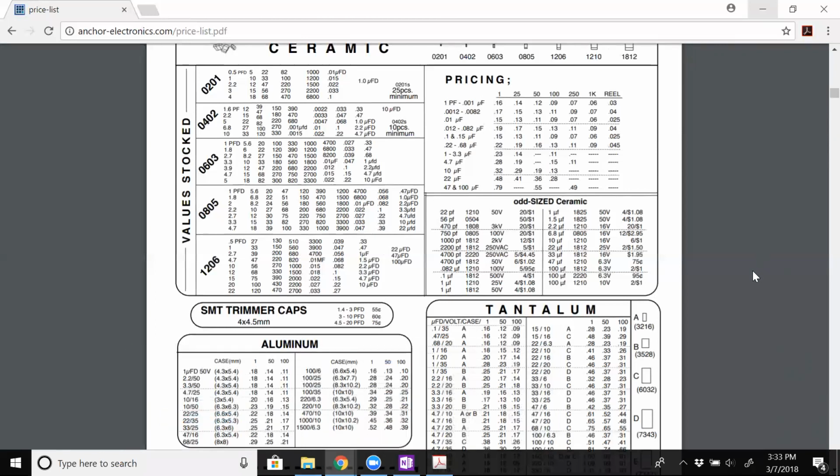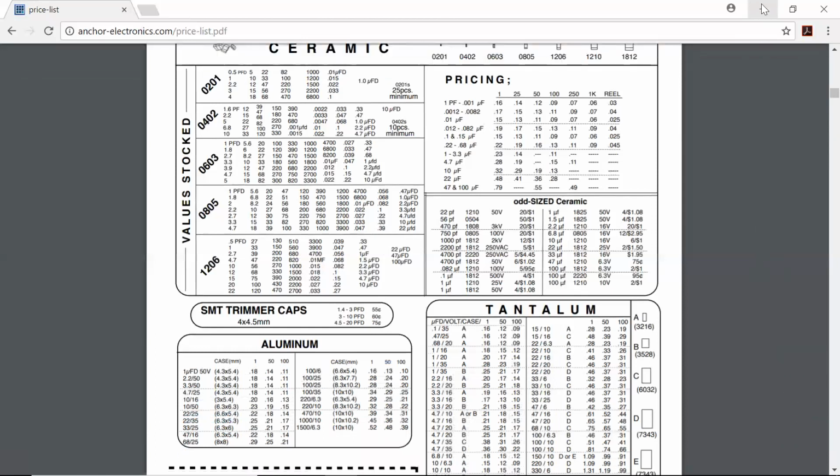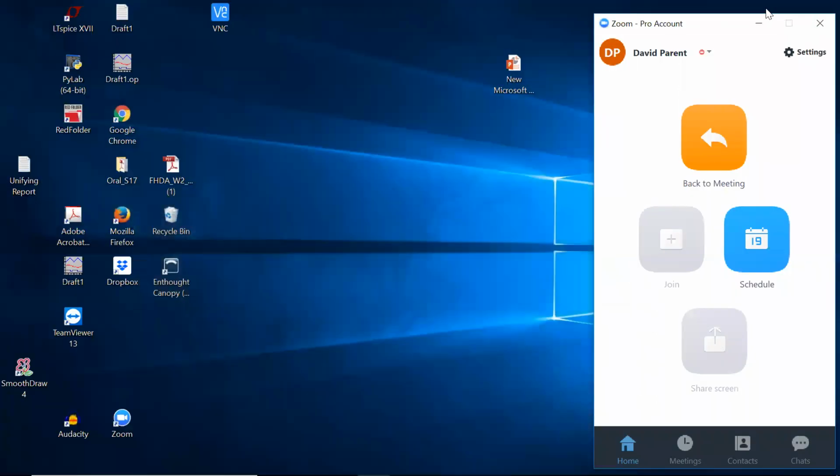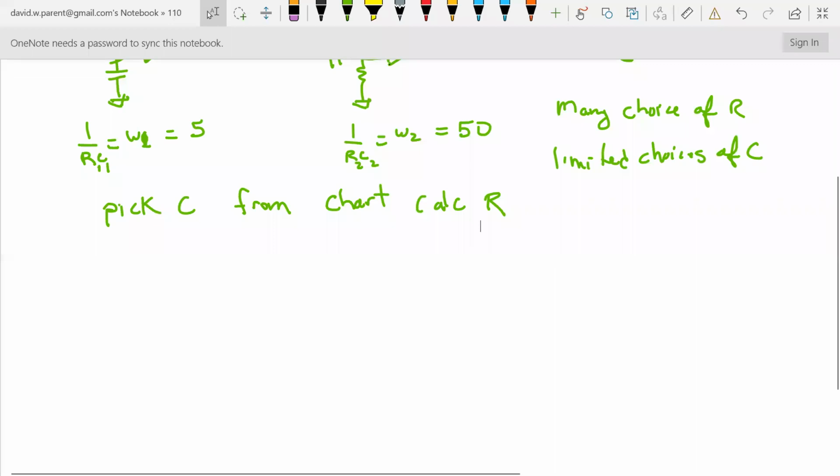And I try to use the same capacitor everywhere, so that if I pick up the wrong capacitor, they're all the same value, right? Through-hole resistors are easy to see the value because you're looking at the bands. Capacitors, you practically need a microscope, and then you have to decode the number. So that's a practical thing. Why do I always use the same capacitor? Because I have screwed it up so many times, I don't feel like screwing it up anymore. Experience has got to count for something.